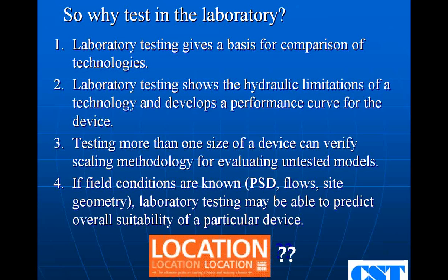So long story made short, when you get in the laboratory, you know what the hydraulic limitations of a technology are. For example, we measured the head in the front and the back of my device to solve a long-running head loss argument. When we got in the lab, we knew exactly what our head loss was. And then you're able to develop a performance curve for the device. That performance curve lets you do some good math and talk about how your device's performance would degrade with smaller particles and how it would improve with larger particles.